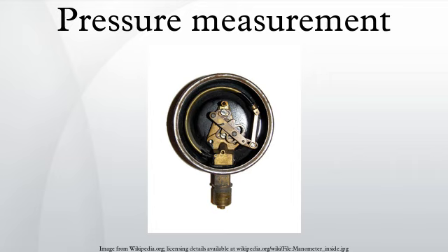A sealed gauge reference is very similar except that atmospheric pressure is sealed on the negative side of the diaphragm. This is usually adopted on high-pressure ranges such as hydraulics where atmospheric pressure changes will have a negligible effect on the accuracy of the reading, so venting is not necessary. This also allows some manufacturers to provide secondary pressure containment as an extra precaution for pressure equipment safety if the burst pressure of the primary pressure sensing diaphragm is exceeded.